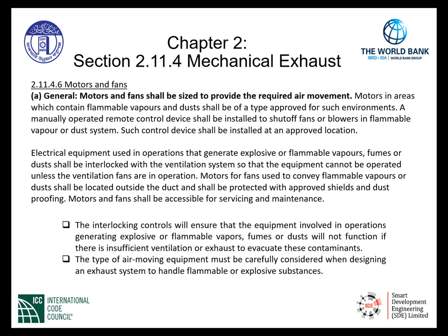Section 2.11.4.6, Motors and Fans. Item A gives us general requirements regarding motors and fans to be sized, provided that the requirement of air moved in these systems is designed accordingly. Motors in areas which contain flammable vapors and dust shall be of a type approved for such environments.